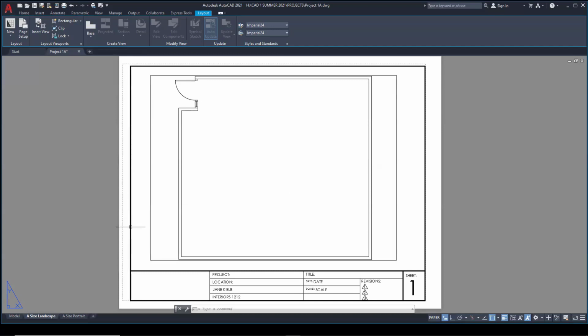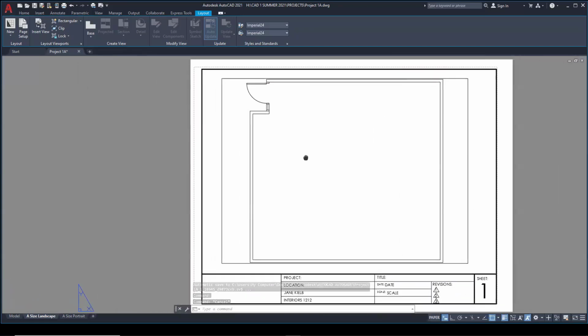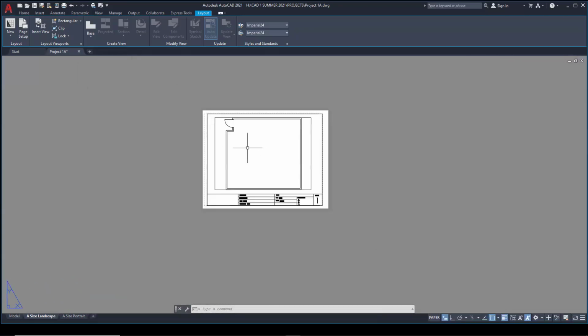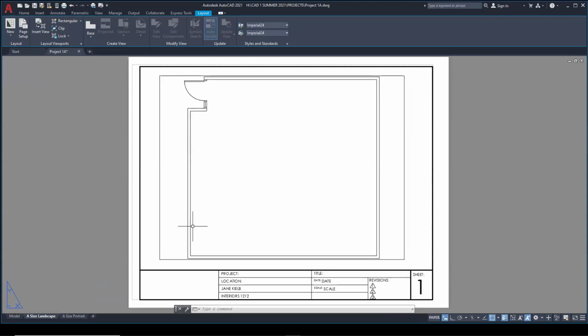So I've got a viewport here. When I hover over it, this highlights, and I have my drawing in here. And when I'm panning, I'm moving my whole piece of paper. And when I'm zooming, my whole piece of paper. But what I can do is edit, or reach through this hole, this viewport, into model space, and I can make some changes.